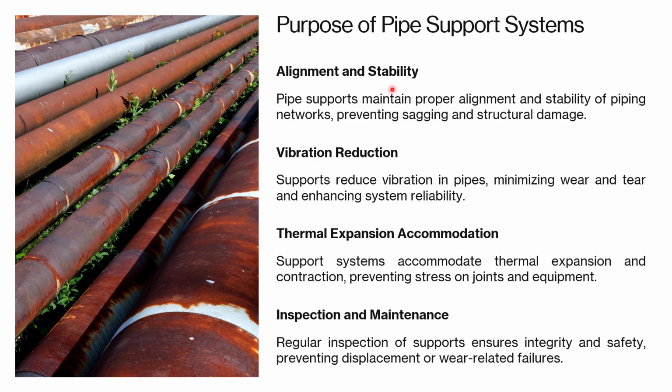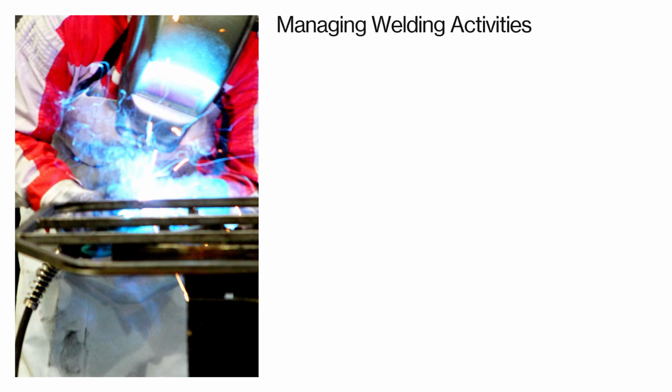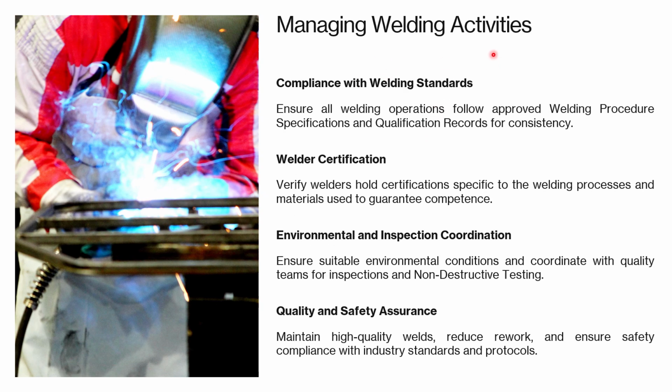So I hope you would have understood the purpose of pipe support systems as well. Moving on to the next one, how do we manage welding activities? Again, welding is like you cannot do anything without welding. If you want to join something, and even if you want to cut something, we use welding. So managing welding activities involves ensuring all welding operations comply with welding procedure specifications, that is WPS. The WPS is your mother document, and second is procedure qualification records, that is PQR. People who are in the welding field would have heard about these two documents often.